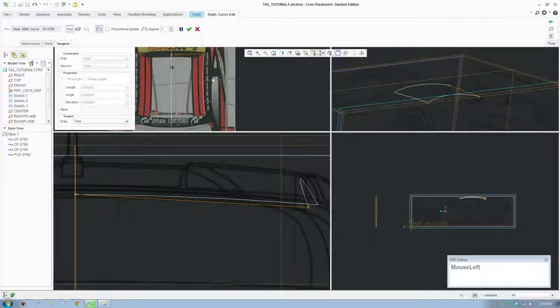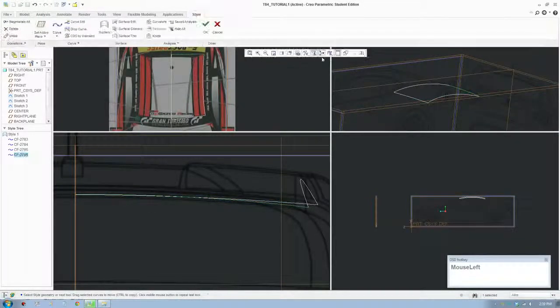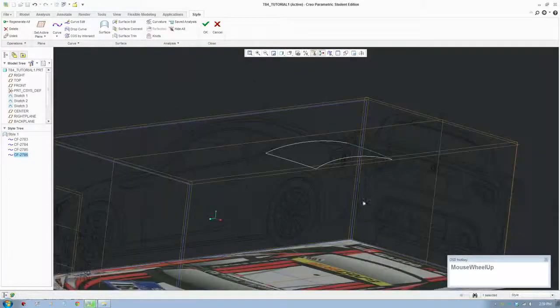We'll do the same for the other line. Click the other line to edit that line, turn on the control points, put this onto horizontal, and make evenly distributed points. Make sure your points are evenly distributed, and don't put too much extreme curvature on it. It won't look well.